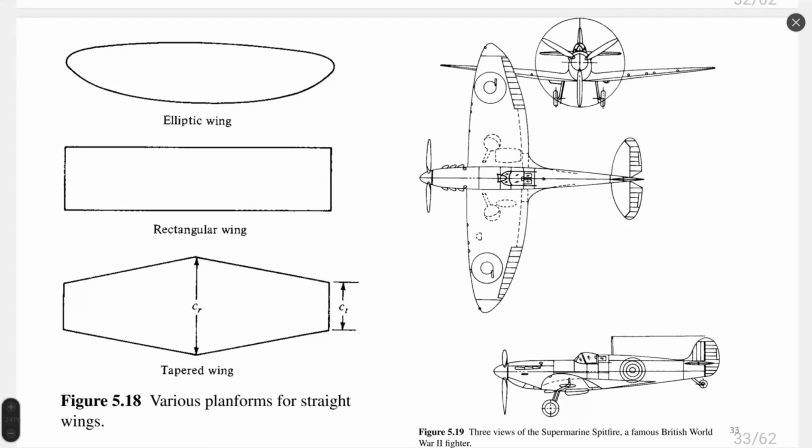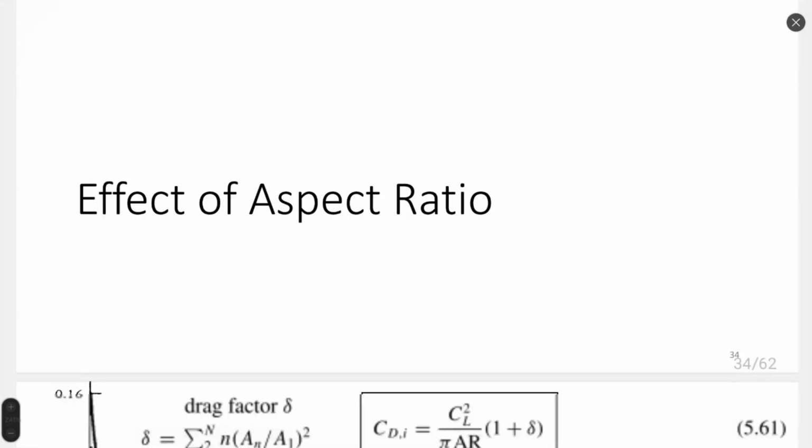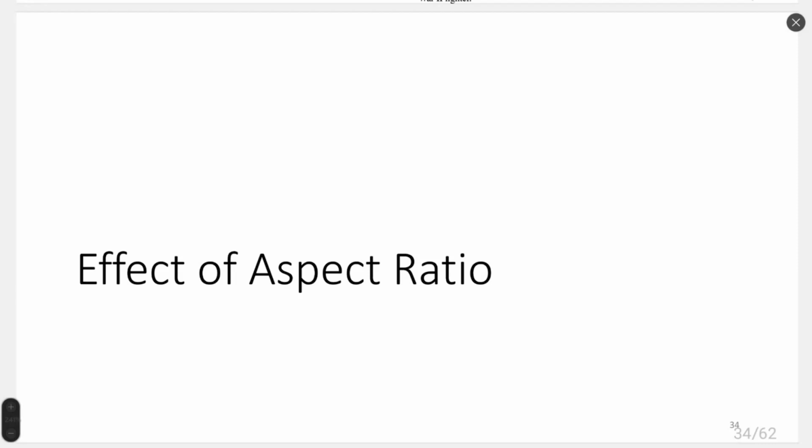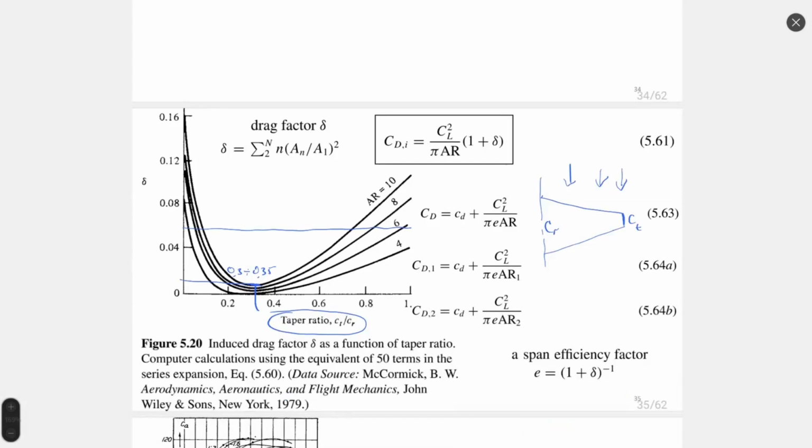If you would like to fly fast, it is not possible because of the nature of the wing, and the wingtip vortex is strong, so you need to have a high power engine, not so efficient with respect to other types of wings. Each structure has its advantages and disadvantages, and there is no best ever structure. Right? So any structure will have some good and not so good aspects.